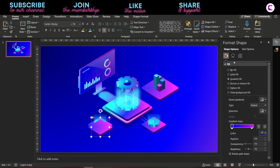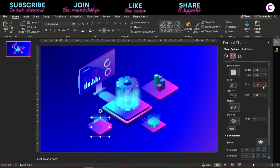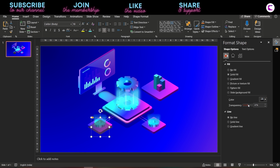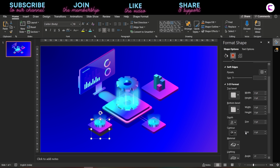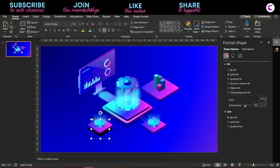Now duplicate this base here and keep the depth to 0. Fill black color, apply transparency effect, send to back. Go to effects option because we have duplicated this item and it has got some effects, so remove the effects material and the lighting, and now increase the transparency and you can see a beautiful shadow effect.